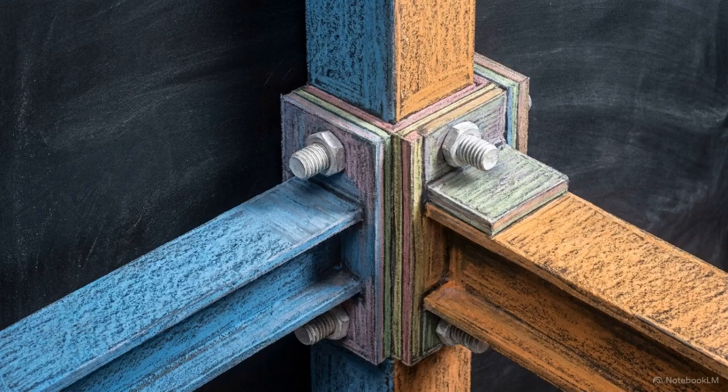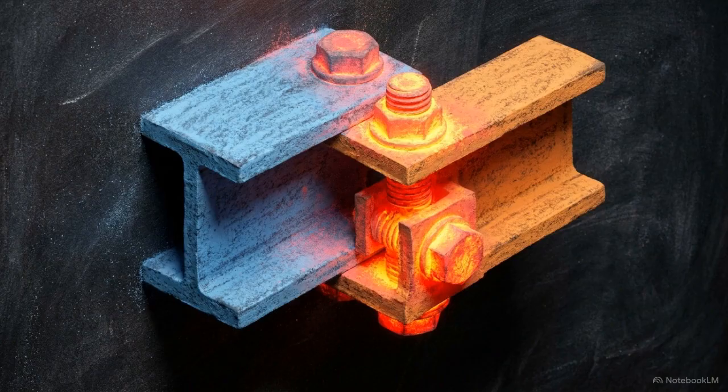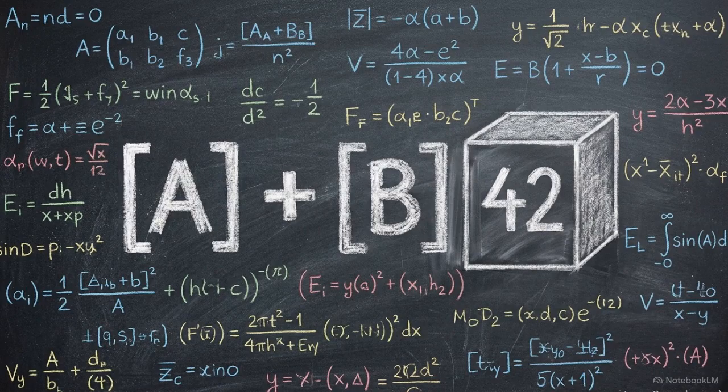This brings us to the principle of superposition, which requires the additive accumulation of structural properties at shared physical nodes. This central 2x2 overlap zone serves as the mathematical joint for node 2, dictating how forces and stiffness pass between the distinct elements. Overlapping matrix terms must be algebraically summed to determine the final stiffness of the joint.